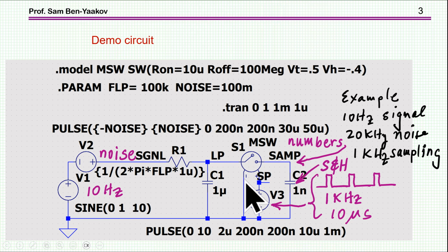So then I've also put here a 1 microfarad capacitor, so it'll be a larger capacitor than this one, and this resistor is adjusted according to the breakpoint of the filter that I'm interested in. For example, the low pass filter here is 100K, so in this case it's quite a wide bandwidth, so actually it's not doing anything in this particular case, but I can change it, of course, to any frequency I wish with this param.